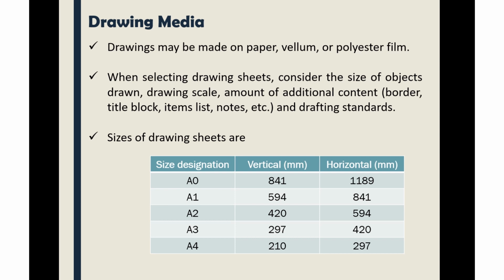When selecting the drawing sheet, you need to consider certain parameters, and one of them is the size of the objects to be drawn. The size of the edges to be drawn should be put into consideration when you are choosing the type of drawing sheet you want to use and the size of your drawing sheet. Also, you need to consider the drawing scale. The drawing scale is important to the size of your drawing sheet.